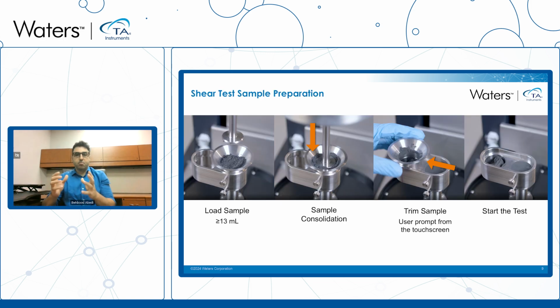The first step you want to do is compress your powder. The consolidation is like an initial condition for that. So how you do it: you pour the powder inside the cup and your funnel, you put your desired consolidation stress, then easily you slide the funnel to the left and you have it trimmed, your powder is ready to use. That easy.